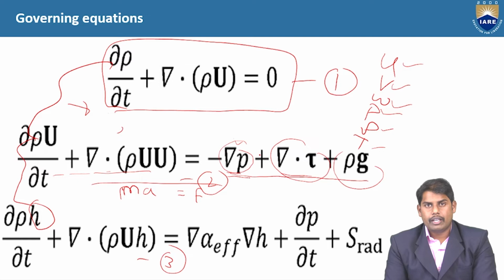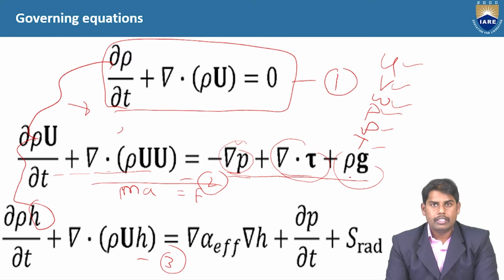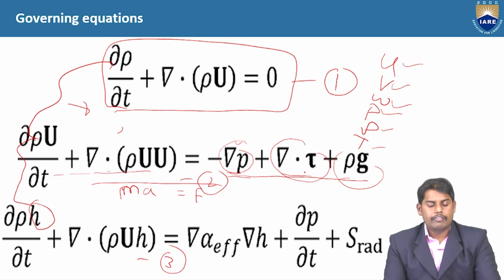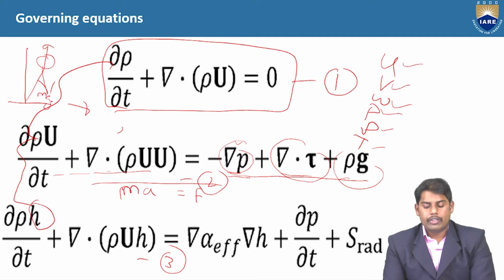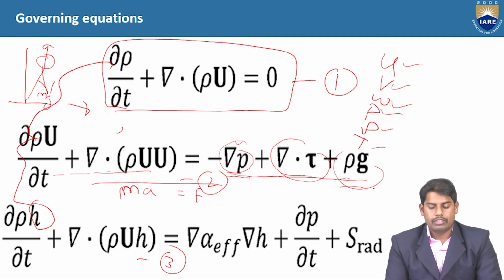Then you have the shear force term. Any fluid particle, if it is passing over a car or let's say a bike, you'll have pressure force and shear force acting on those bodies. And for the body force, depending upon the flow phenomena, we will take the gravity force. For example, if you have a vertical heated flat plate, with the flow going vertically, the gravity force will act on the fluid particle and pull it vertically downwards. So here you need to use the body force term, which is rho g. This is very important.